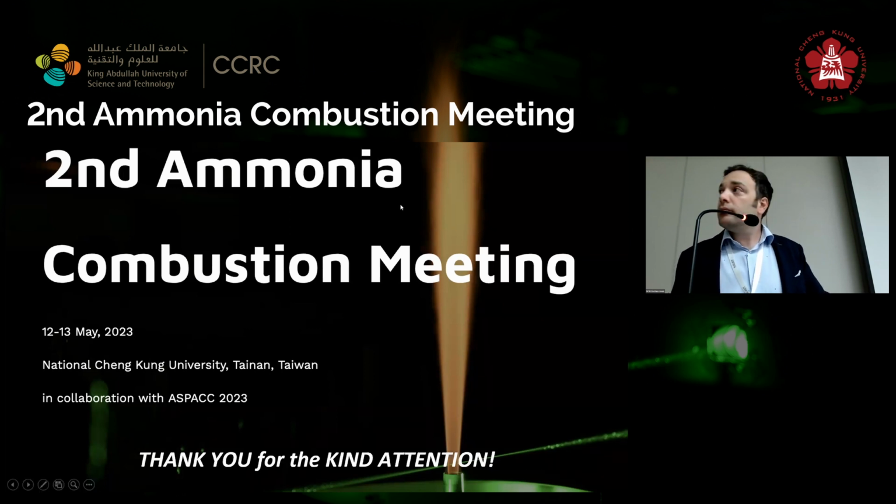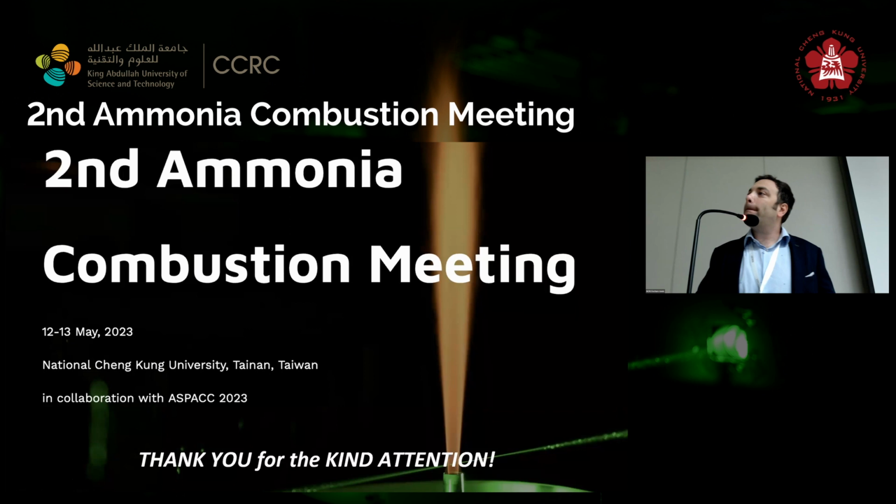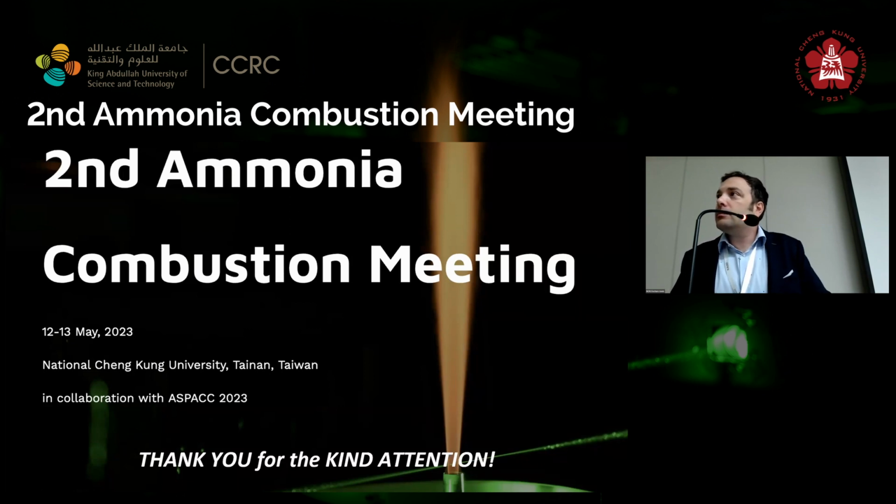Okay, I could start. So it's no surprise that ammonia lends itself to mild combustion quite well for the reasons, of course, you articulated. In your work, have you looked closely at what happens to NOx? Of course, now you have two components. Of course, keeping the temperature down, you're killing most of your thermal NOx unless you have hot spots. But what are the measurements and how is NOx being seen under these conditions?